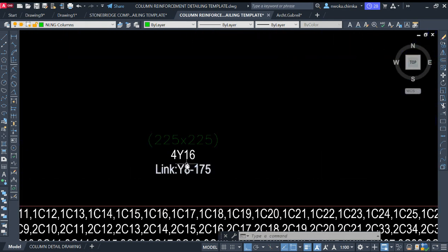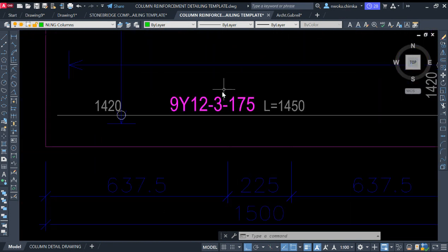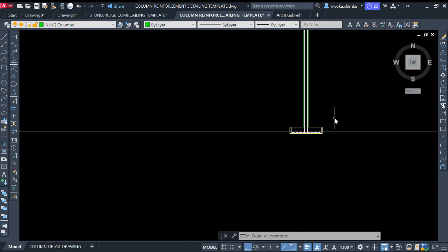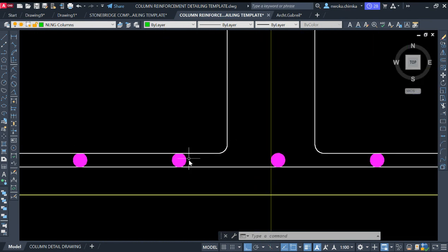The size of the column reinforcement is 16 diameter, while for the footing it is 12 diameter. So that is why this is 12 diameter. That's why I use 12 diameter for this curvature and 16 here for this place.